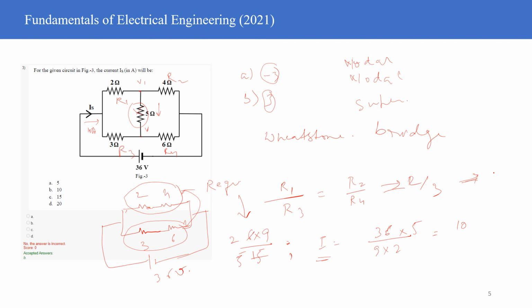Sir, the query about the Wheatstone bridge is that there is a 5 ohm resistance to be connected between that two loop. So the voltage is to be, as per your point of view, 0 in that case. No, across the 5 ohm it will be 0, right? The voltage difference across the 5 ohm is to be 0. Sir, let me know why it is so.